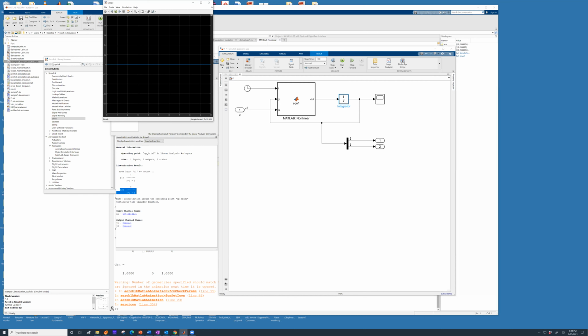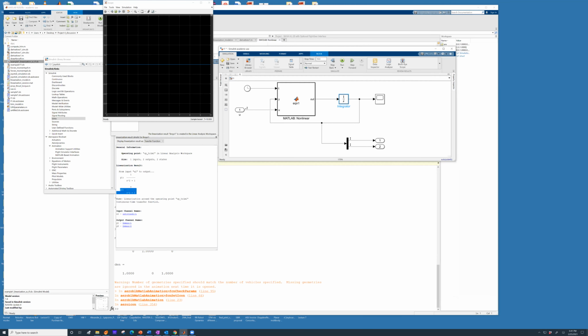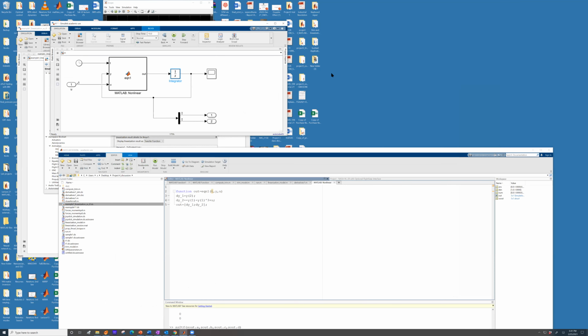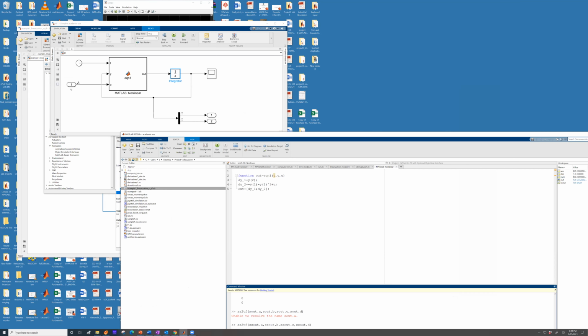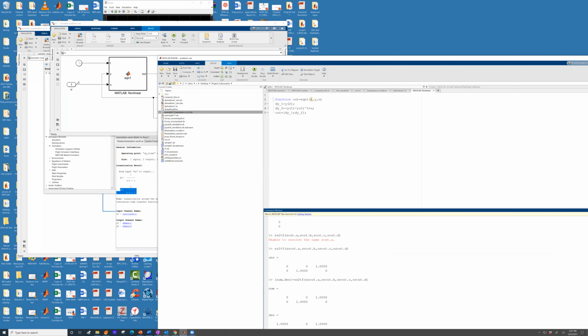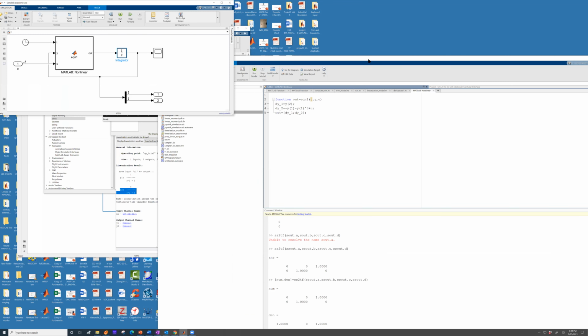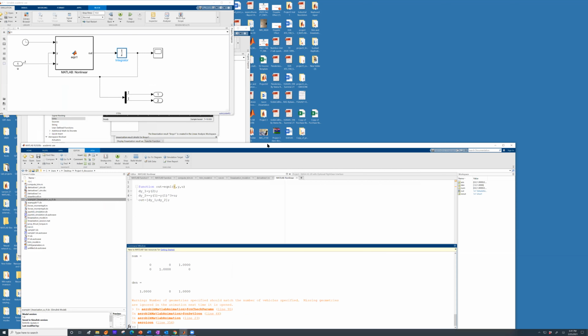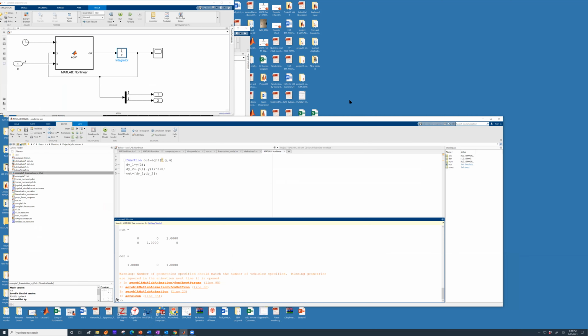Now I'm going to go to command window. So I will show you both. So I have this Simulink file and I am working at the command window. This is my Simulink file and I'm working at the command window. Now, to answer Zubir's question, you have to sync with the model. Only then the initial conditions will get updated or Matlab would complain.